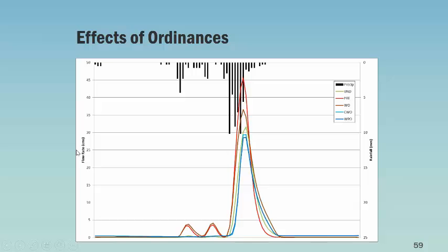As you can see in this slide, the flow rate, in cubic meters per second, before 1974 in pre-development, could get as high as 45 cubic meters per second. The axis here is in hours, so each one is an hour, and the rainfall is in millimeters on the right-hand side axis. So there is a huge difference, almost 40% difference in the peak flow, between the fully protected land versus pre-development, for example.